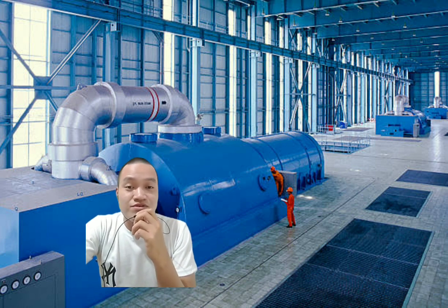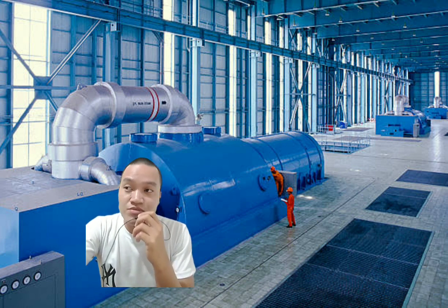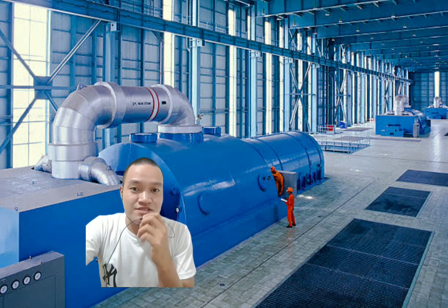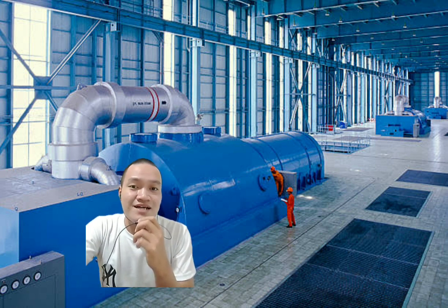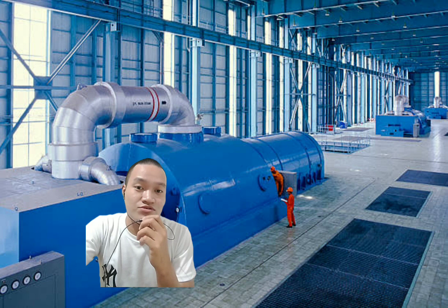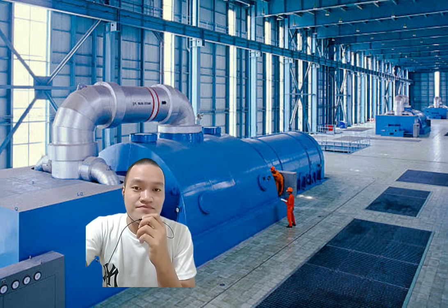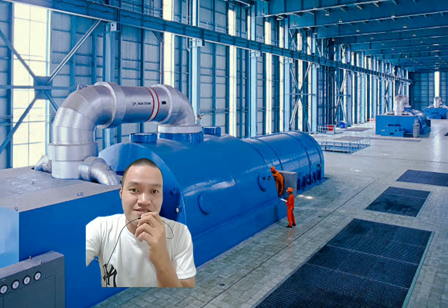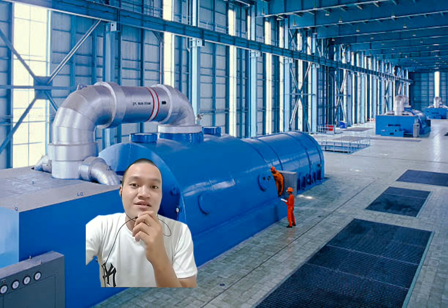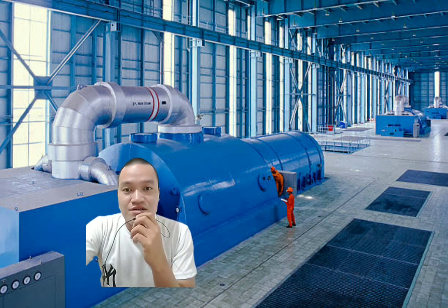This also involves bringing into use the turbo alternator, which uses steam removed at some stage from the main turbines. Then a check should be made on the expansion arrangement, and the drains should also be checked to be closed. So the condensate recirculation valve should be closed and the astern steam valves tightly closed also.